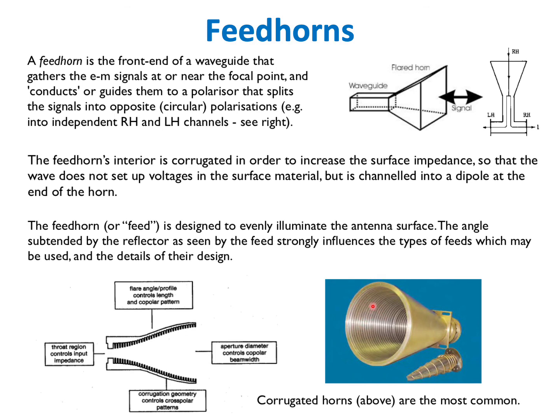If you see these ridges inside this feed horn, which you can see here in this diagram, those are to make sure that the electromagnetic waves coming down into the feed don't couple to the feed itself. They're just directed down the throat of the feed instead of, say, setting up a standing wave inside the feed.